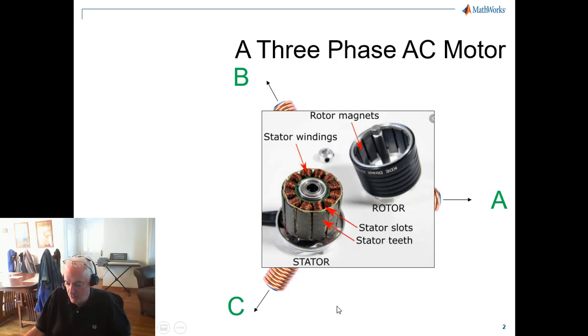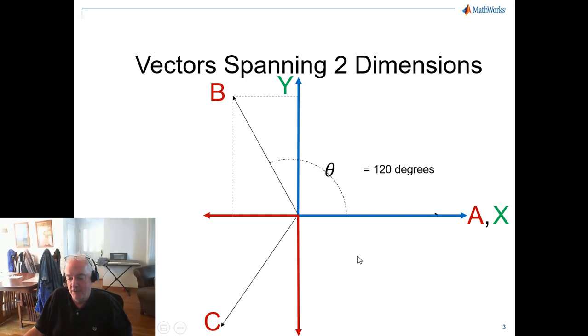All right. And so with regard to moving into this vector mathematics, I do want to emphasize that what we're doing now applies equally well, and maybe even more effectively, when you consider 12, okay? Because each of those 12 windings has its own individual orientation, and therefore the reduction that we're about to observe, as we show that 3 can be reduced to 2, also applies as 12 can be reduced to 2. So the efficiency of reducing things through vector math is even stronger when you use real motors with additional pole pairs, right?